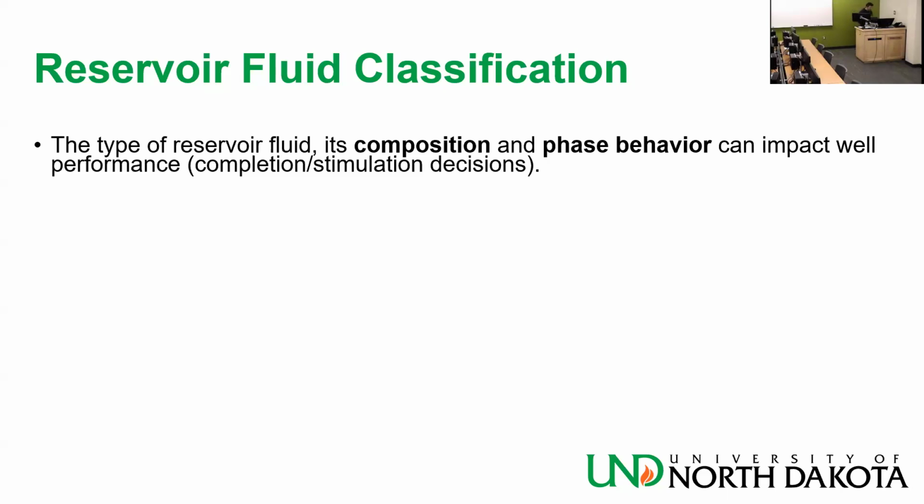H2S is a little bit like the sun. If you get heat stroke once, then your tolerance for the heat, for the sun, drops. Same thing with H2S. If you get hit by H2S and survive it, your tolerance goes down. So next time you're gonna be hit earlier, at a lower level, etc. And there are all sorts of standards that you need to know. Well, I had them memorized when I was young, but I don't remember them right now.